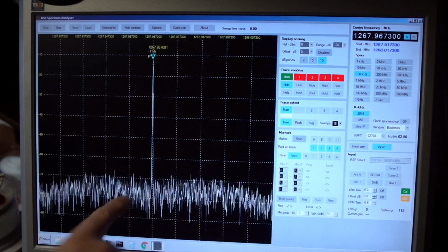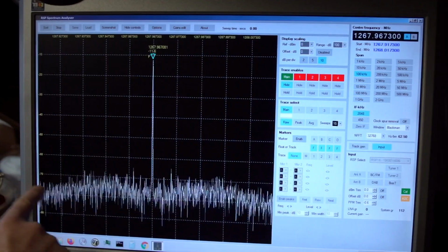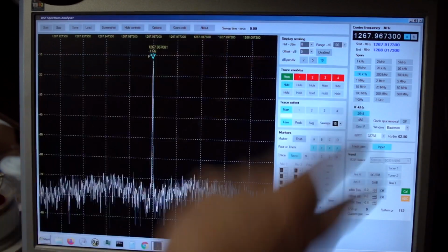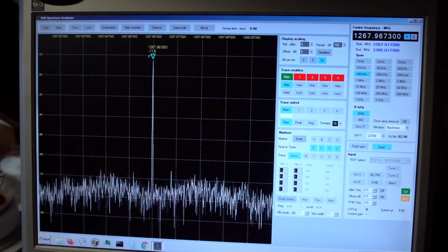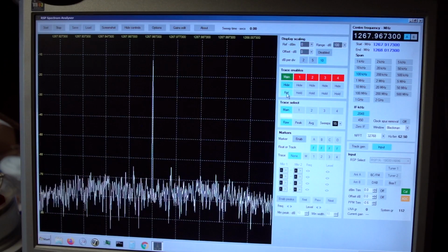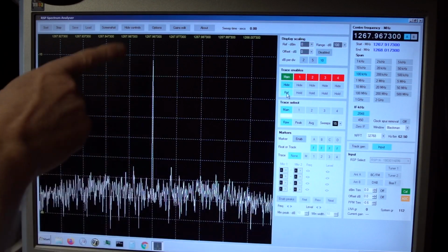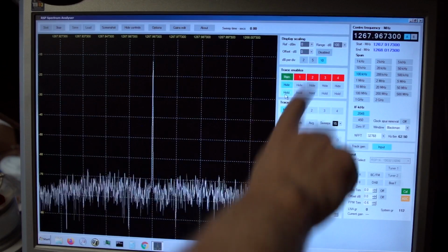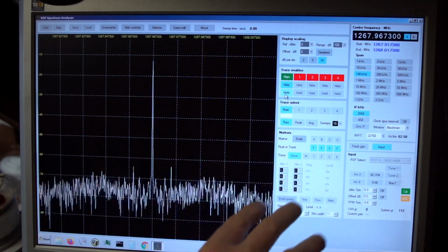So this display is actually showing us amplitude, and it's showing us the frequency on the x-axis. With software like this, with more modern spectrum analyzers, you've got the ability to do things like freeze frame, a bit like a storage scope, where you can actually freeze the whole thing and then you can go in and do some analysis, and it's not changing all of the time. We'll release that, and there you go. And you've also got memories and traces and lots of mathematical functions as well.